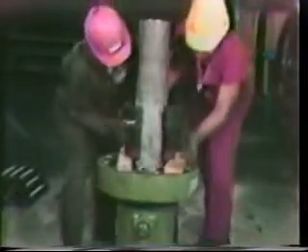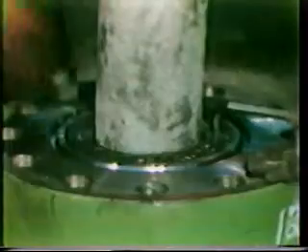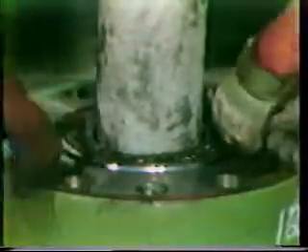As the casing is lowered, the slips are forced against the casing, increasing the hold or bite on the casing. If extreme loads are to be exerted by the casing string, two sets of slips used in tandem may be necessary. The hanger is hinged, enabling it to be placed around the casing and not over the top. Once placed around the casing suspended in the hole, it is dropped into the bowl in which it will seat.